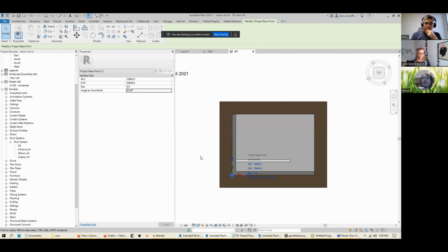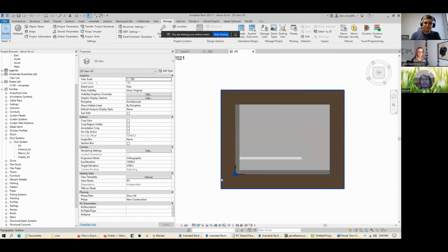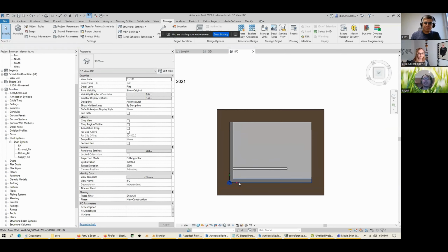The architect should not be responsible for doing that, but they should have that awareness to ask the surveyor as their responsibility. And they should have all those numbers down in writing at the beginning in clear correspondence. Here are all the numerical values that can be checked. And later on, when we talk about dropping things into Revit rather than starting from Revit, everything should just work. And there should never be any manual rotations happening in Revit, never any manual data input into Revit or IFC for that matter. It should just be correct because the surveyor has done their job correctly. I absolutely agree on that.